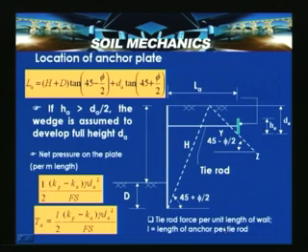So, now the tie rod force per unit length of the wall can be determined by using this expression. Ta is equal to (Kp minus Ka) into gamma dA squared by factor of safety, times L, where L is the length of the anchor plate per tie rod.